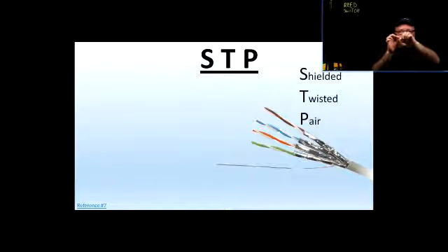If you take another terminal off that terminal, and you also connect that to the grounding terminal of another device, that device is also technically grounded, but because it doesn't go directly into ground, it goes through another device, it is called bonded. That's just FYI. Right?